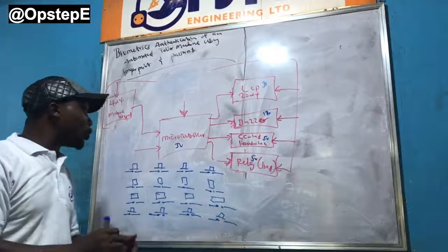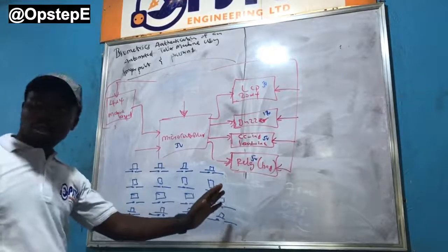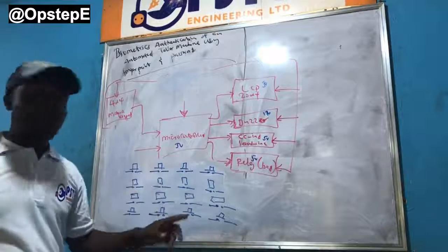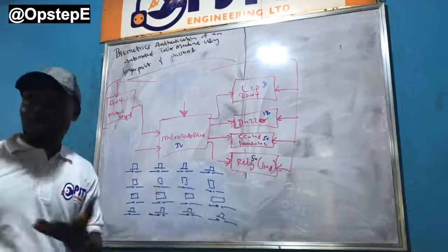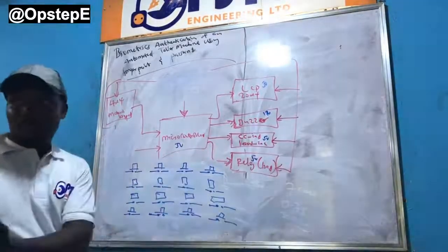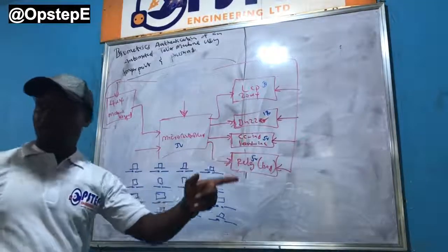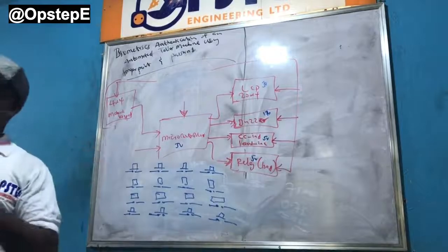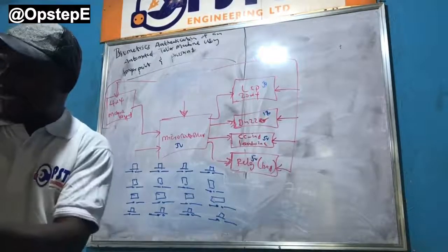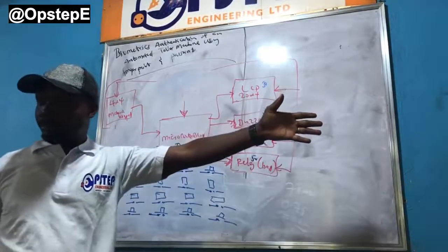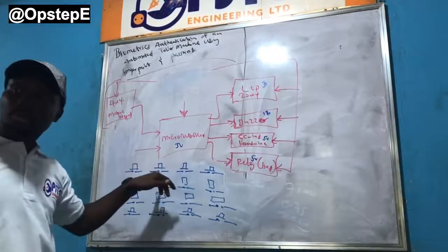What it means is that if I need to actually use this switch, 16 times 2 is 32. I'm going to need 32 different wires running from this guy to the controller. If I take all the ground, each one to ground, that will be 32 divided by 2, which is still 16. So I'm still going to need 16 pins to the microcontroller if I need to use a switch.